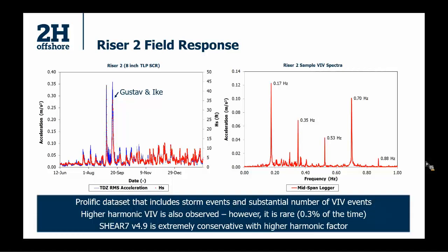Again, you can see the excellent correlation between wave and the riser acceleration. We did not observe good correlation with the current on any of the risers, and hence I'm not showing you a current versus acceleration plot. So as I said, we observed VIV.